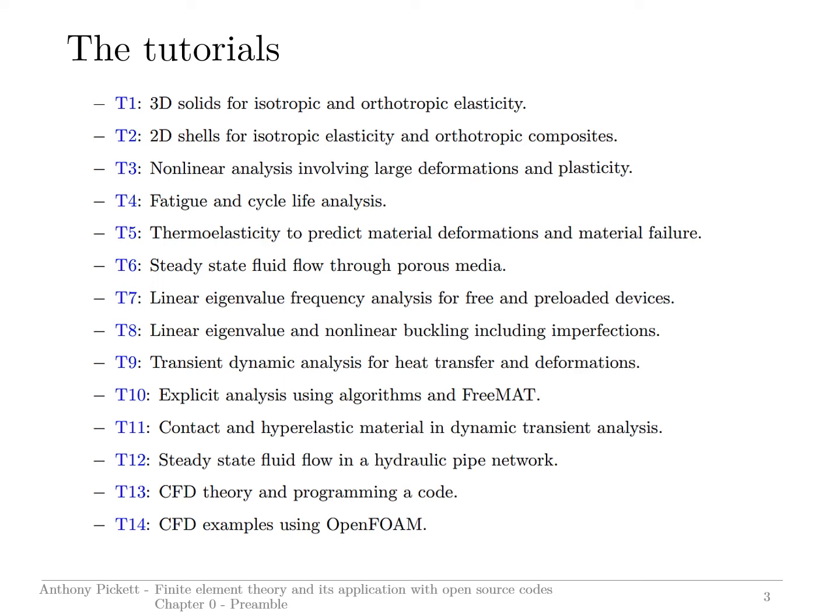In tutorial 13, we first look at programming of a simple CFD code taken from a reference. And then in tutorial 14, I move on to analysis using OpenFOAM within FreeCAD for different pipe systems and also flow over an aerofoil. So it's a bit of a wrap up on the different tutorials. And just to emphasize again, I try to tie each of these to the theory presented in the first part of the book.